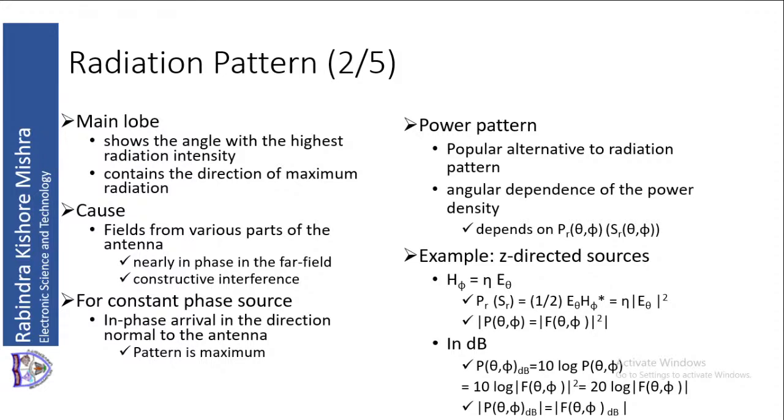If we consider the amplitude part only, then P(theta, phi) in dB is equivalent to F(theta, phi) in dB in terms of distribution. The factor of 20 we drop. The reason is simple: the distribution does not change, only the amplitude will change. If we consider the normalized part, P(theta, phi) is equal to F(theta, phi) in terms of dB.